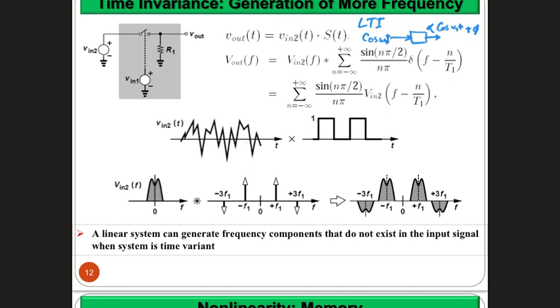The important thing is to notice that in frequency domain it's confined to a band that we see here around 0, okay? Now, when the convolution happens, you also need to get the frequency domain representation of this square function. The square function is a periodic function, and each period has a square, right?